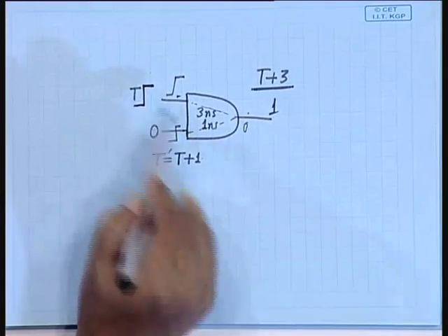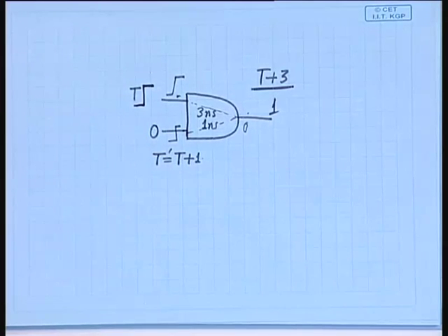So, even though at that point of time it appears that the output will not change, you still have to schedule the evaluation event, right. So, that is actually in a way bad news. Why? Because you have to keep on propagating your events and you cannot filter them out by looking at the present values of the inputs. You still have to propagate it, because in the meantime your other inputs can change and they can change faster, resulting in some updation when that event is finally taken up.